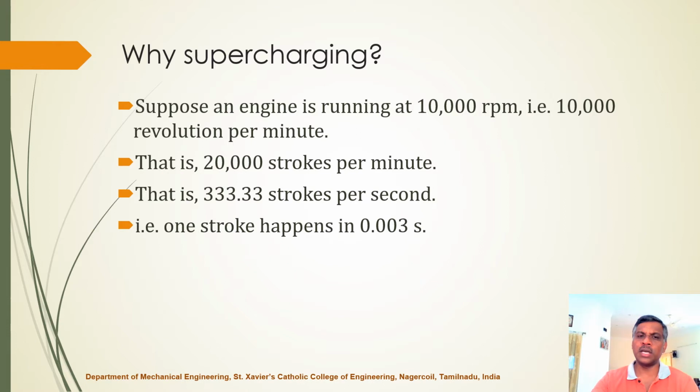In that sense, one stroke is taking just 0.003 seconds. So suction stroke, we talk about suction stroke, piston moves from TDC to BDC, and inlet valve opens and the air is aspirated into the cylinder, we say that way. But you see how much time it is allowed, 0.003 seconds. So that is very small, 3 times 10 to the power minus 3 seconds. That is only for 10,000 RPM.